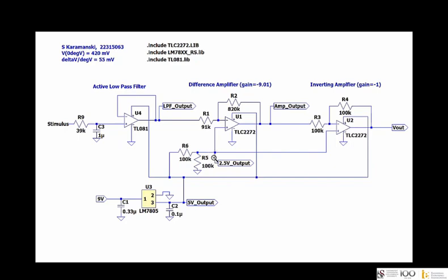and it doesn't have an effect on the circuit. So for example, if you had an op-amp buffer over here where my mouse is hovering, then that would mean that the output would almost see a perfect voltage source, and then the input would see an infinite resistance over here. But in this case, I don't think it matters much because I don't have any other resistors loading the circuits. But if you had other resistors loading the circuit over here, then these resistors would have an influence, and then the current draw would be different.